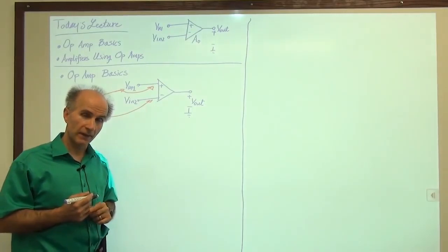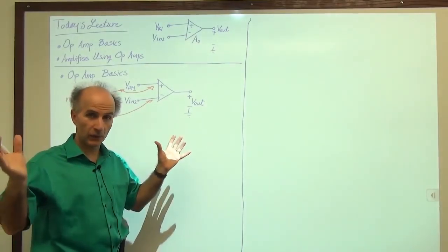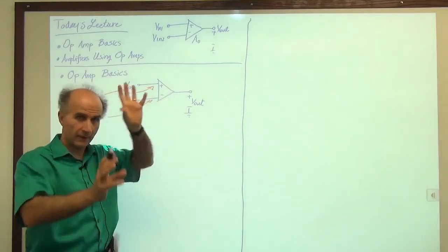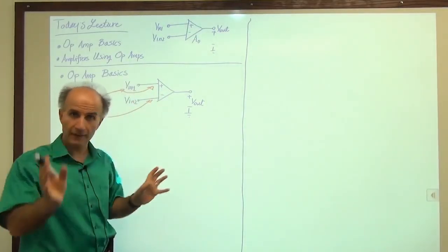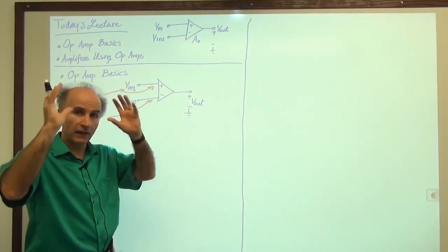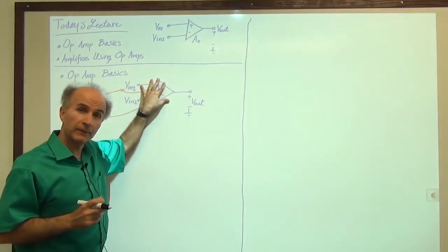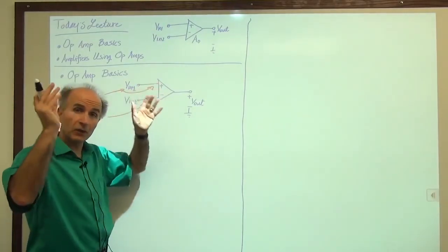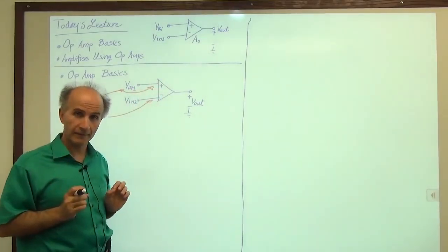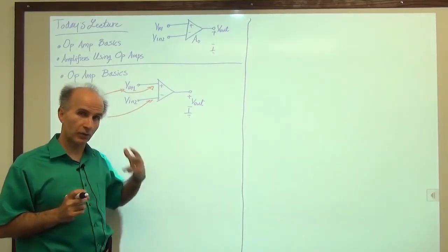And the other is that sometimes if we have a complex circuit consisting of lots of transistors and stages, etc., if we, in our mind, can simplify that, or view that as an op-amp, then that circuit becomes easier to analyze. So these are the two advantages of having this op-amp picture in mind.